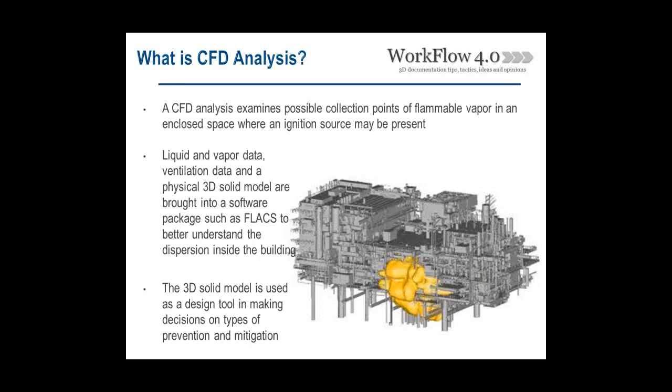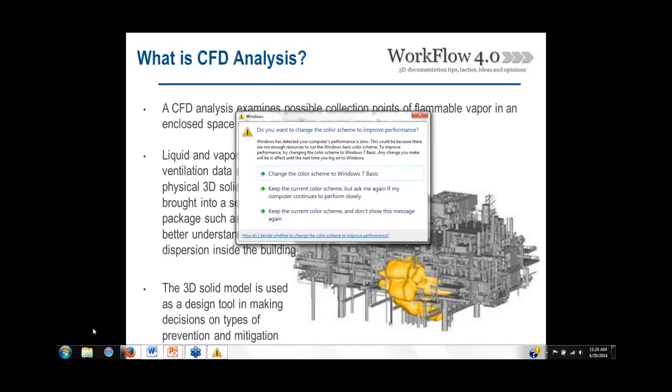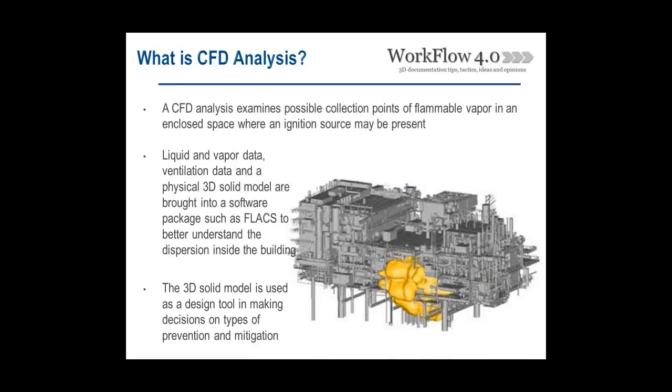CFD stands for Computational Fluid Dynamics, and it's used to understand cloud movements inside an existing facility. A software called FLACS was used to simulate the cloud dispersion. Some of the requirements are to collect all ventilation ingress and egress points and potential leak points, and of course to use the 3D model.